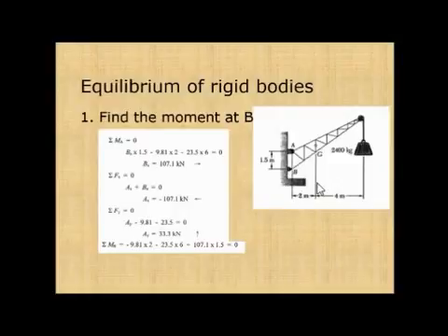As this system is not moving, the net force at point A should be 0, obviously. So for point A we need two forces, a force with the direction. Let that force be Bx into 1.5, that is the distance, minus 9.81 into 2, that is acting along the center of gravity, then minus 23.5 into 6. Similarly, you can find the moment of forces for a number of systems given in this picture or in some other pictures.